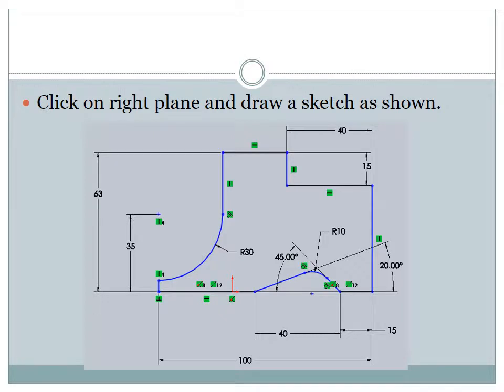The basic primitive for the part is a rectangle. Yes, draw it, extrude it, and then go back and do three extruded cuts, or do them all in one sketch if you prefer. Pay particular attention to the geometrical relations shown. Using these is often the only way to draw a part from what's been given in the drawing.